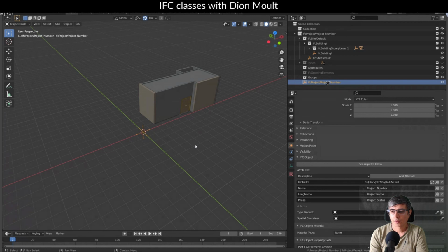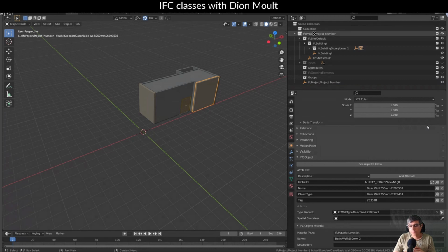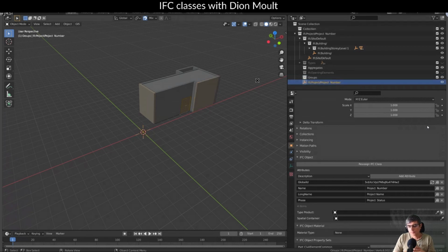But you can also have something called a project library. These are ways of containing data, or BIM assets, or material libraries, or things which do not belong to one particular project, but can be shared across many projects. This is a great way for people to distribute government standards or company standards in an openBIM format. Now, unfortunately, not a lot of people are using project libraries. So for today, we won't talk too much about that. We'll talk just about an IFC project.